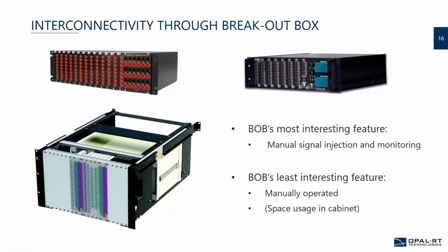That way you can save on cost while having one set of mobile breakout boxes, for instance, and reuse them on different benches. The only thing you need to keep in mind is that you need to have the same type of connectors to connect to the different test benches, or do patch harnesses to interface, depending on your design approach and how you're managing the benches that you have in house.